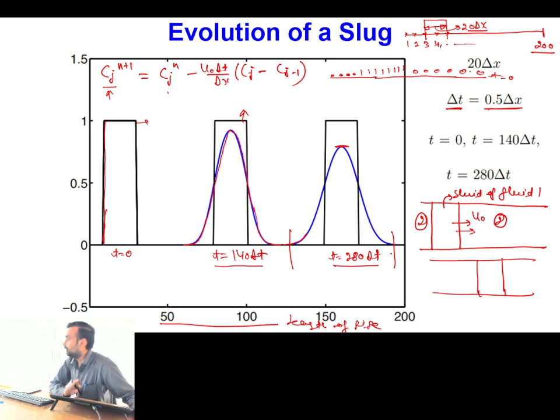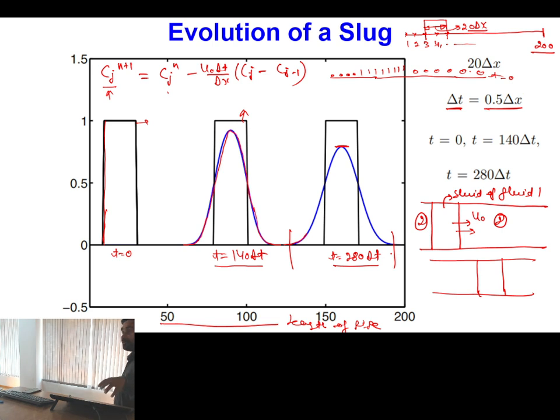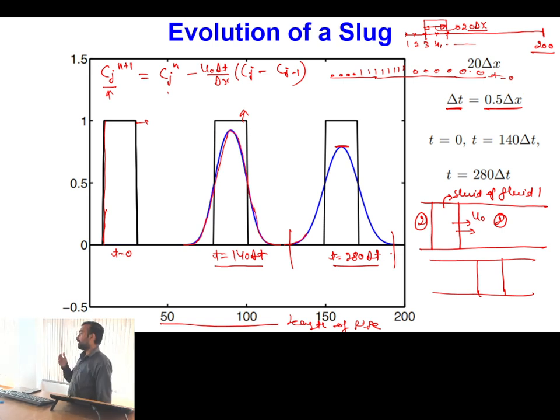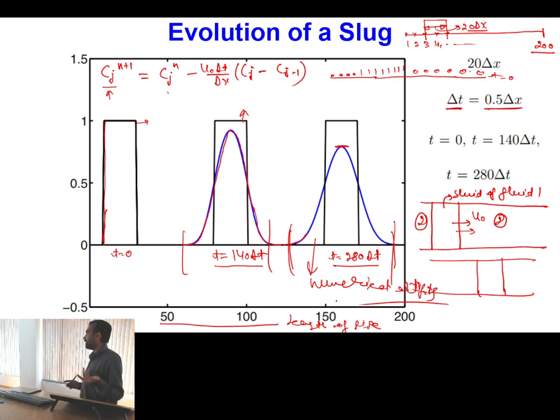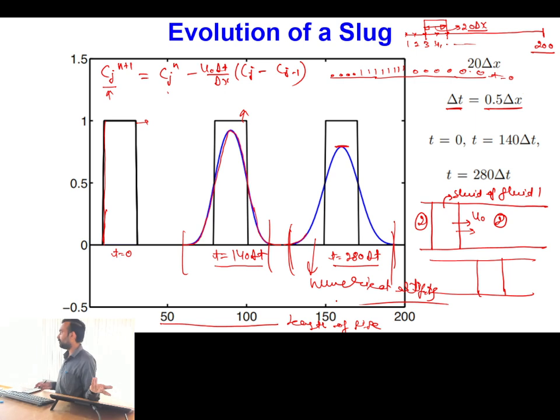Is this point clear? So it means that this is a very simple problem. For this type of simple problem, whenever I am using the upwind differencing scheme for advection of the color function, when this solution is marching with time, the color function is actually spreading in multiple cells. Okay, so what is this? All these are nothing but numerical artifacts. Okay, it should not have happened. This is a very simple problem. This should not have happened.